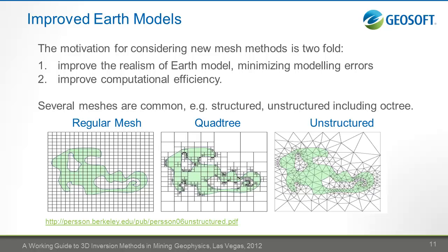In the octree method we do a little better than this. It's essentially the same process. However, wherever we want more resolution or better approximation to the surface, we divide the cell of the voxel which the surface cuts in half in each dimension, and repeat that process until we have our desired resolution. And in the case of unstructured meshes, of course, we can make our elements a piecewise approximation to the surface.